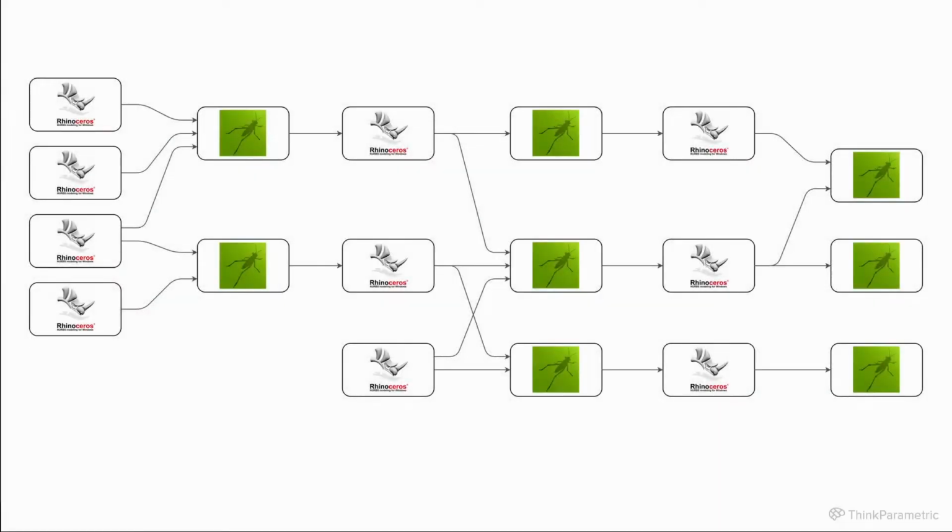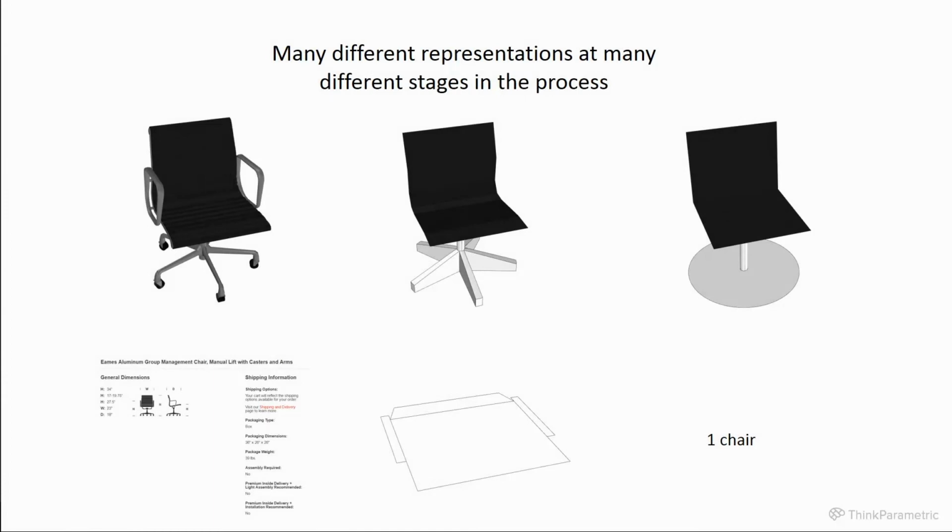In our process, we basically zoom out a step and consider a Grasshopper script to be one node in the graph. The outputs of the nodes are stored in a Rhino model, which can again be used as the input for the next Grasshopper node. Now, why is it so important to distribute the model over many smaller models? I will try to explain that.